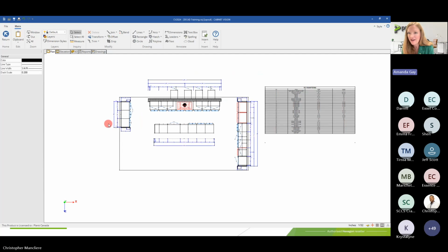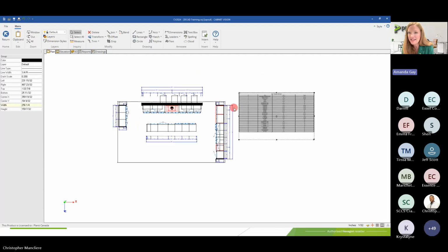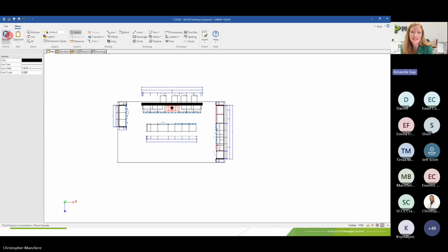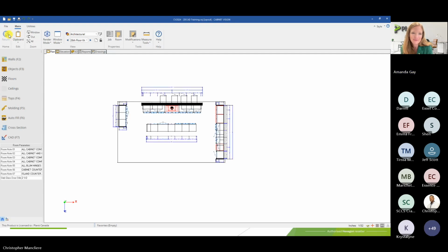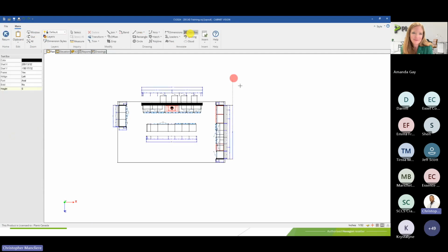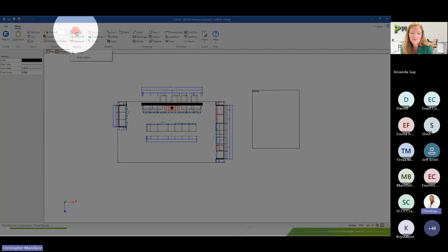Okay, and we have, is there a way to remove the lines around the text box? Yes, it's in the properties of the text box. So if I go to create a new text box and let's type some text, by default you have the line, but if you reselect it, so you click on the select command, click on the actual outside edge of the text box.